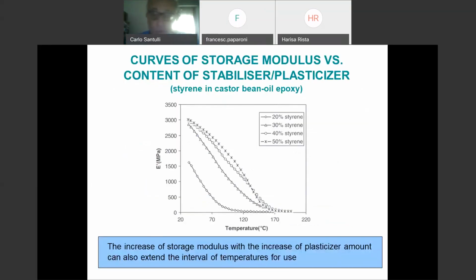Of course, you can also try to stabilize the material, because in practical terms, in this case, we have an epoxy. So basically, we don't have a glass transition temperature because it's a thermoset. So it's cross-linked, and it doesn't undergo any changes between the glassy structure and the rubbery structure. It deforms very little, so it's closer to the glassy structure than the rubbery, but it's much stiffer. You can get to a few gigapascal.